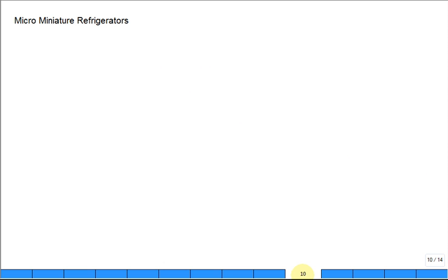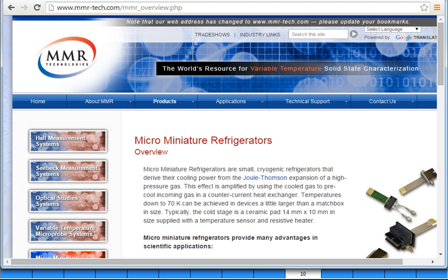Where do we find the Joule-Thomson effect for cooling? Well, you just do a quick search and you can find these things. Before they had good turbo expanders, they did just a lot of Joule-Thomson expansion for cooling and even did it to get down to cryogenic temperatures. It was tough. It was really tough. Okay, but they did it. But then as soon as they could make some poor turbo expanders, they introduced them and left the Joule-Thomson behind.